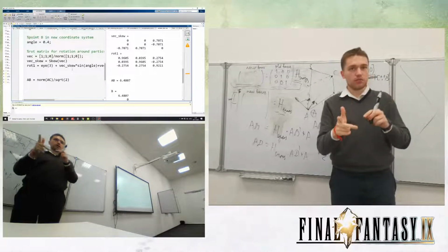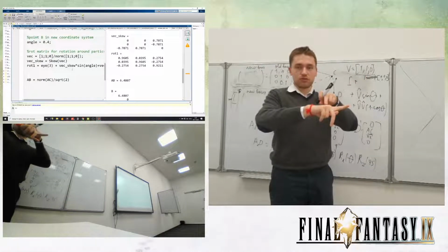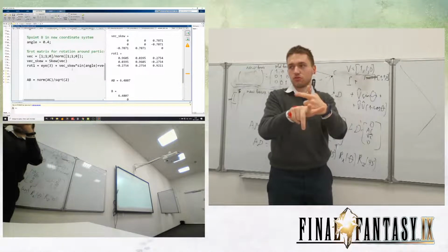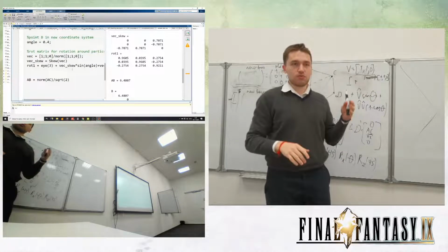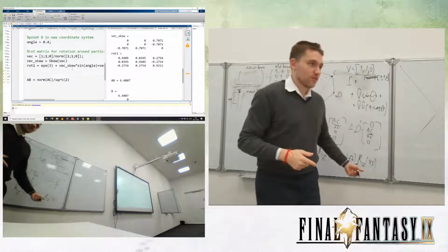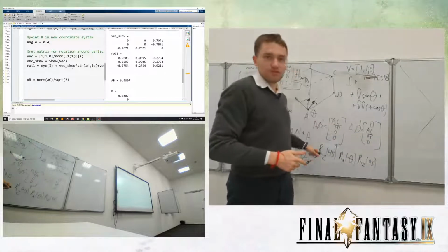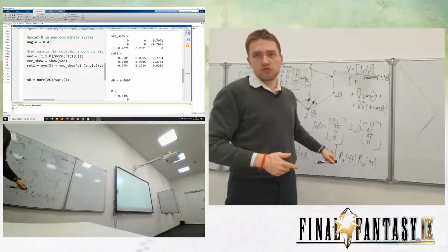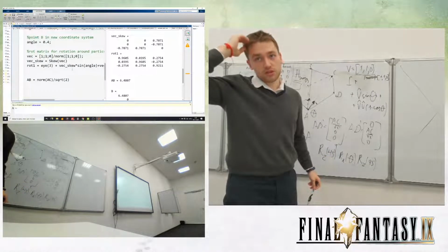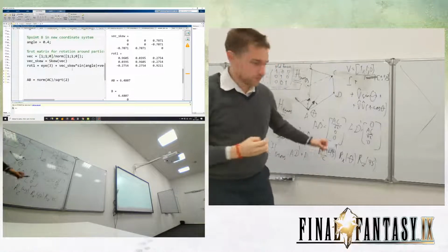But in the fixed angle case, we rotate around the fixed, original axes, and we can return to the initial position. The difference between Euler angles and fixed angles is that you need to write them in a different manner. If you write from left to right, it will be Euler angles. From right to left, it will be fixed angles. Actually, you don't need it in non-robotics applications most of the time. Maybe in some data science part, but I'm not really an expert in this part.